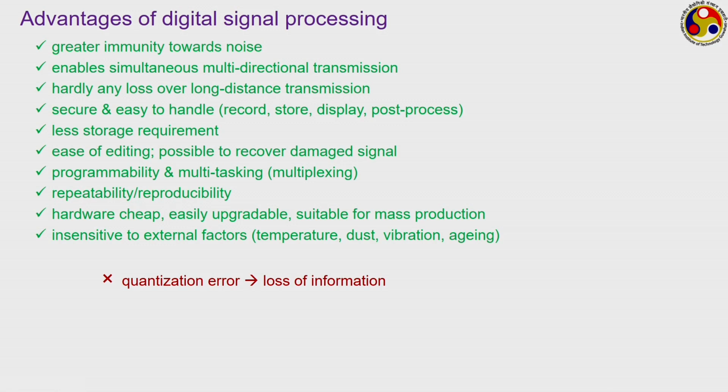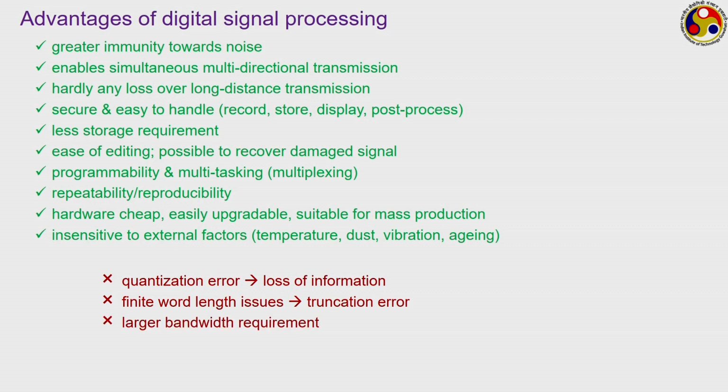One is the quantization error, which is not present with the analog signal. Quantization leads to the loss of information. What we mean by quantization, I shall be coming to in the next slide. Finite word length issue leading to truncation error, again I shall be discussing this later on. Bandwidth requirement generally is a bit larger for the digital media. They are difficult to synchronize.